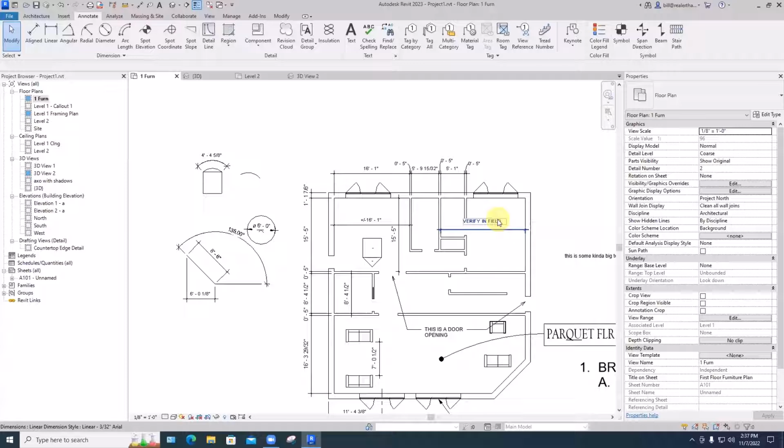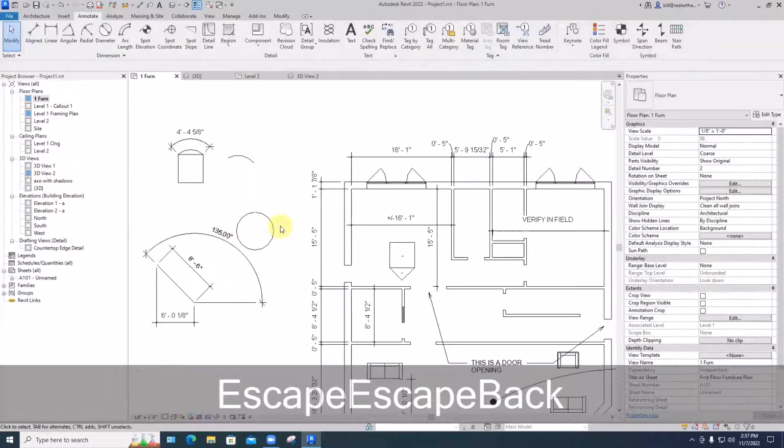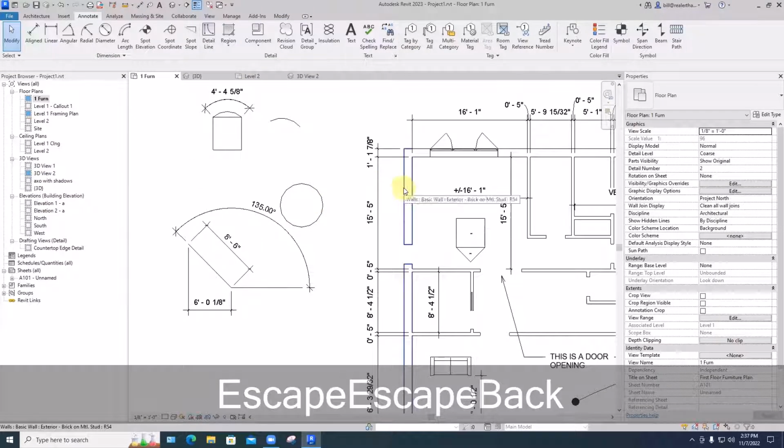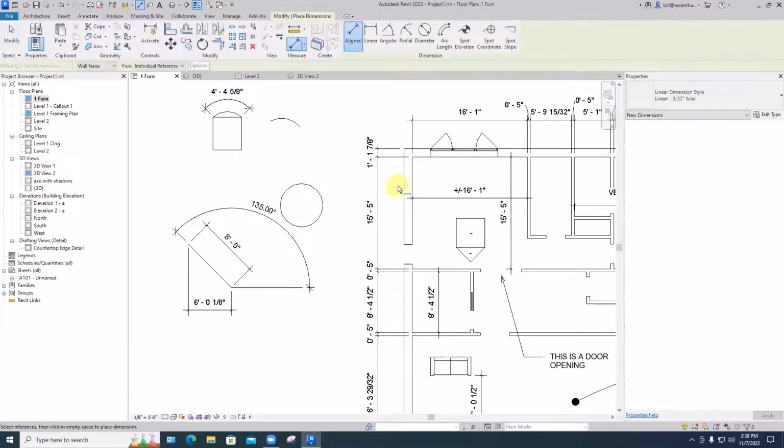One thing I would like to point out is, unlike AutoCAD, where I can just say, give me a dimension from here to here, and it would create it, Revit won't. Revit only dimensions two things, either the face of it or the edge of it. And sometimes it's not necessarily what you suspect. If I want a dimension from the wall to here, I'll do the wall, and it's either going to pick the center or the point that's perpendicular to the wall right there.